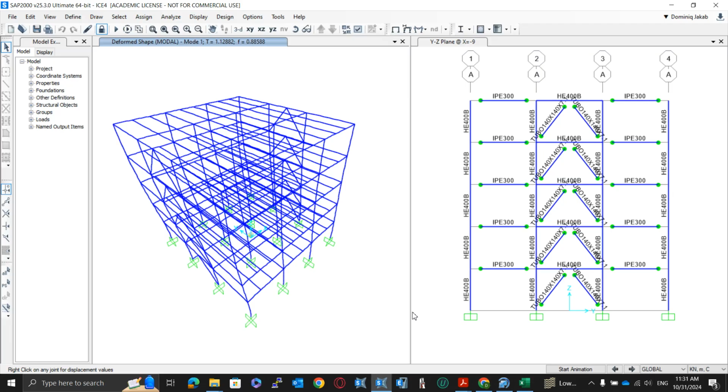But let's discuss a bit regarding the structural system. If you were to bet before running the analysis, what would have been the dominant direction? Do you think this is the correct direction for the first deflection, for the fundamental mode, or the other direction on the braced frame?